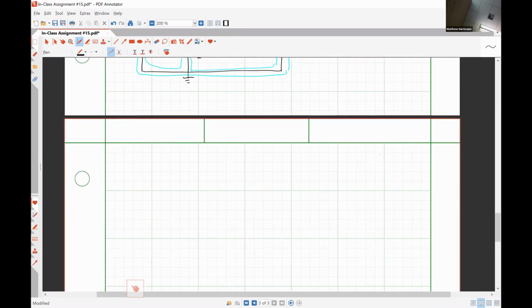We've already determined that LEQ was 3 henries times 1 henry over 3 henry plus 1 henry, because our inductances were in parallel. That gave us 0.75 henry. To look at our equivalent resistance, we're going to need to take our equivalent inductance out of the circuit and then look at a dead network.